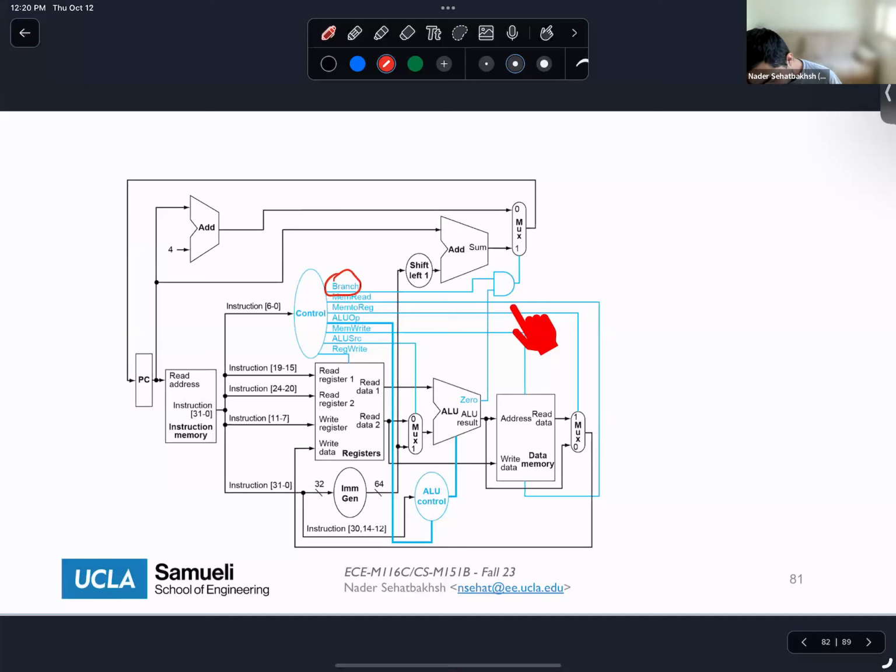Not really. So here is a 4-bit value, okay? This is what the ALU understands. The ALU has a table that, based on the 4-bit value, decides which operation to perform, okay? But in order to generate this 4-bit value, we first generate this 2-bit value, feed it into the ALU controller, and then the ALU controller generates this 4-bit value for us. So the ALU controller is really not optional here. It's there for generating that 4-bit value, okay? But we are doing it in a two-step approach, as I said, to make things simpler for us.